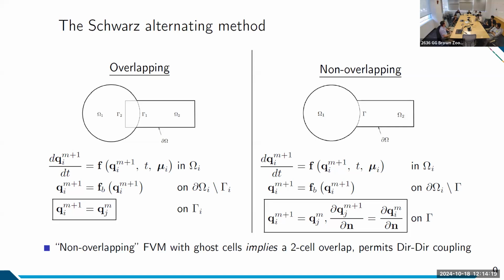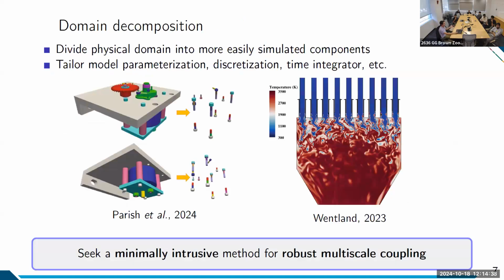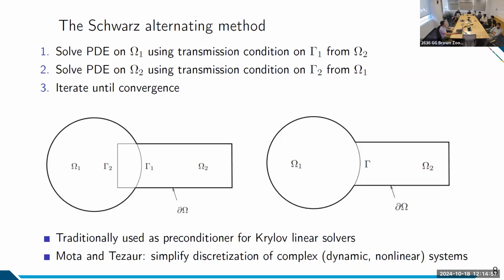But the nodes inside the intersecting region, they are not constrained, is that right? No. That's the whole point, that these subdomains can be meshed entirely independently, and you don't have to worry too much about what's in the other subdomains. I see. So in the case of this bolted assembly, you can mesh a bolt and not have to worry about what the frame's mesh is. So there are really no constraints except on your mesh quality. The more you refine your mesh, the more accurate your solution is, but that's true in any case. Okay, good. Thank you.